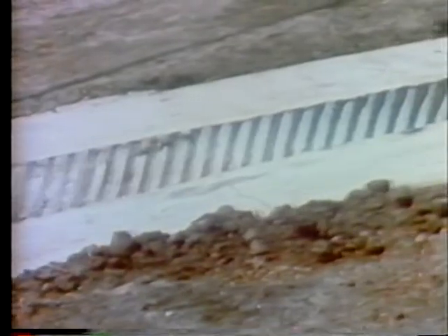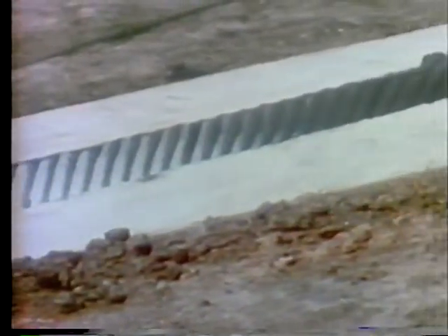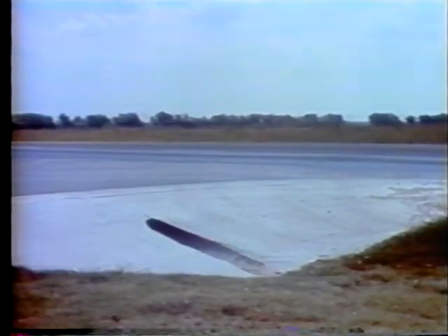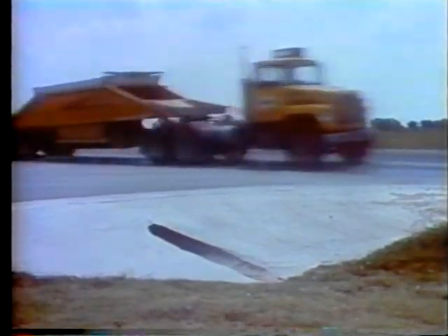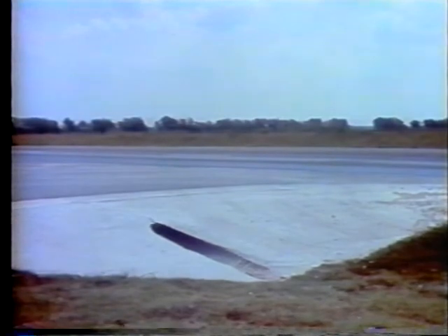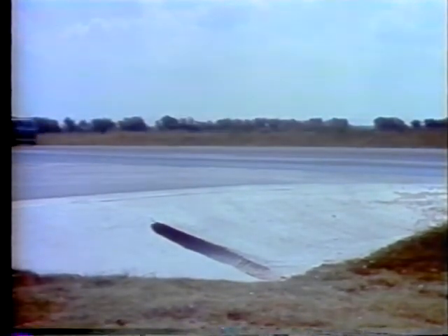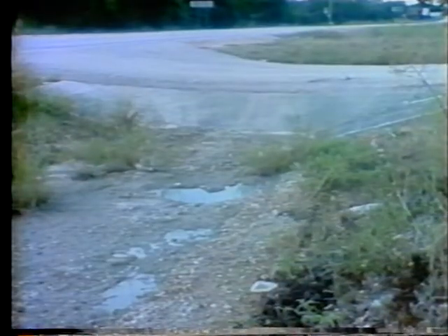Embankment slopes which can be struck head-on by run-off-the-road vehicles should be constructed to a 6-to-1 or flatter slope. A 10-to-1 slope is desirable. Even better, where low water flows are involved, installation of a paved low-water crossing is often less expensive than a drainage culvert and completely eliminates the safety problem of the culvert end.